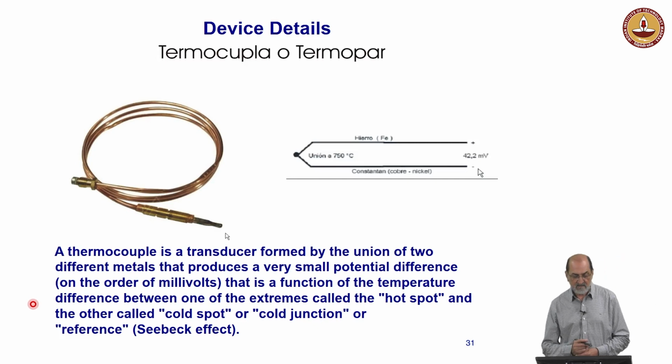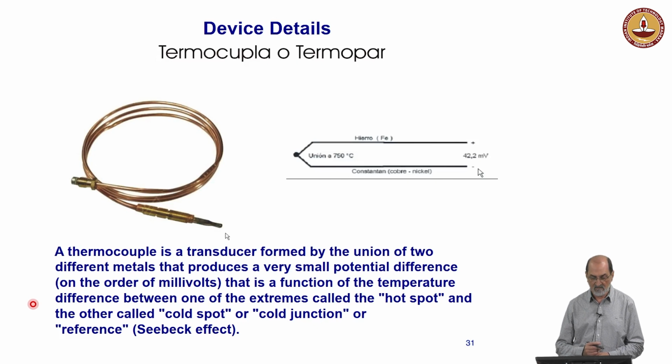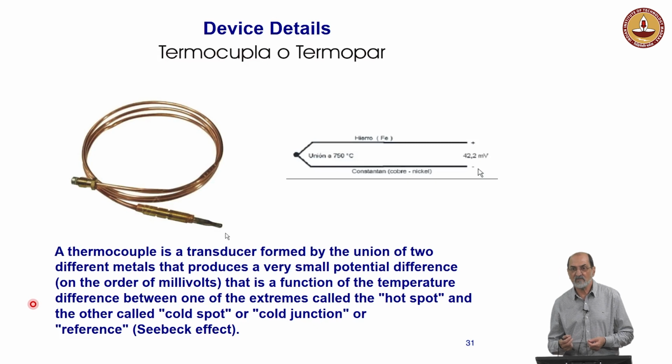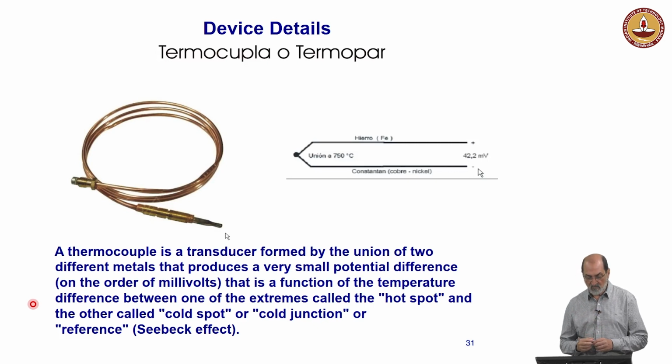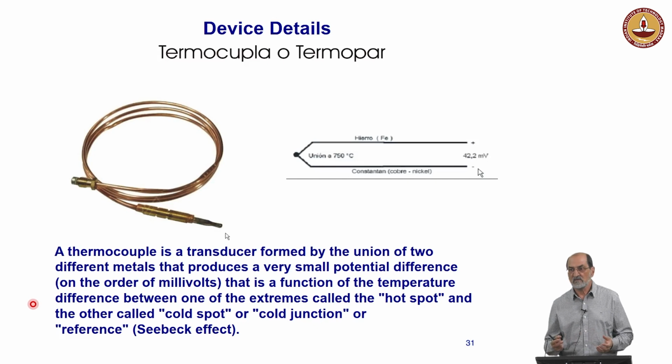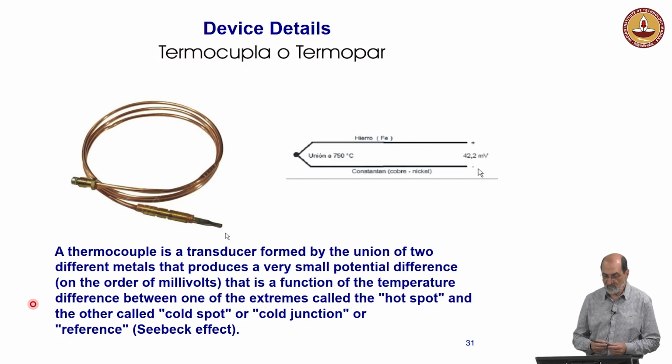So these are the typical devices we use. I don't know if you use this here. A heater has a thermocouple. As I mentioned, a thermocouple is just a junction between two kinds of metals. When this is hot, it produces a potential difference, and this can create a current, and that current goes to a solenoid, which keeps a valve open. So when for some reason the burning stops, automatically the thermocouple stops sending that voltage to the solenoid, and the valve closes, and there is no more gas running through the heater.